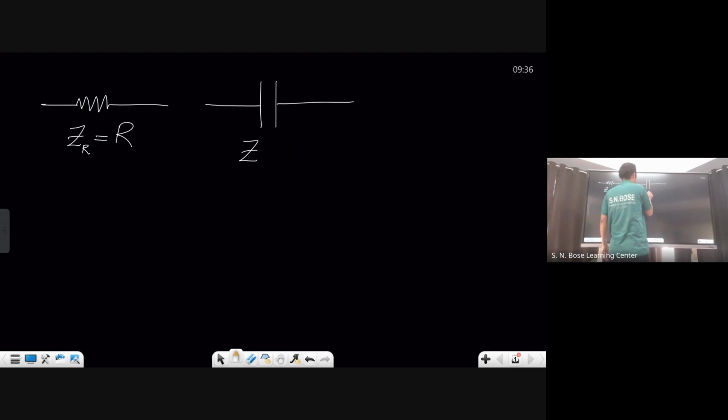Resistor of resistance R, capacitor of capacitance C, ZC, that is minus j by omega C. Why? How did that minus j appear? Because, what is that? Voltage was leading or lagging? Voltage was lagging. Capacitor, voltage was lagging. Minus j by omega C. They can throw very basic questions. You got a point. Now I'm thinking about building this one and going into much more sub circuit, but you understand the basic question: what happens in pure capacitor, inductor, RL, RC circuit and all.